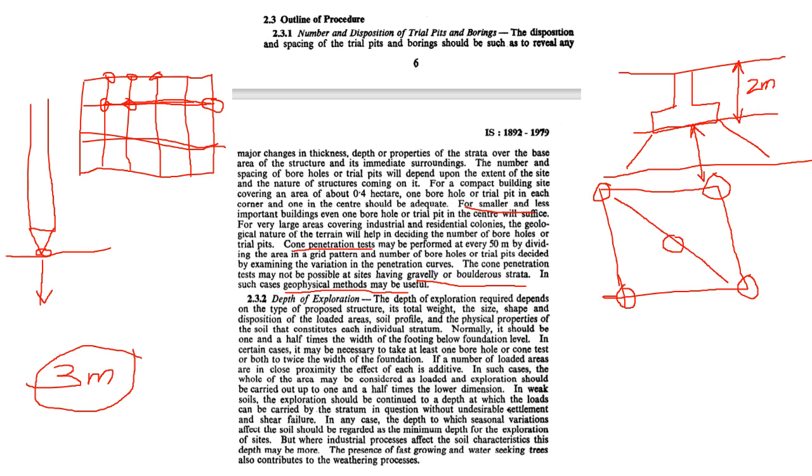So it is not just the soil at which your foundation is resting which should have sufficient bearing capacity, but also, suppose your load is getting transferred like this, and maybe up to another 3 meters. Actually, up to the next 3 meters, your loads will be getting transferred.